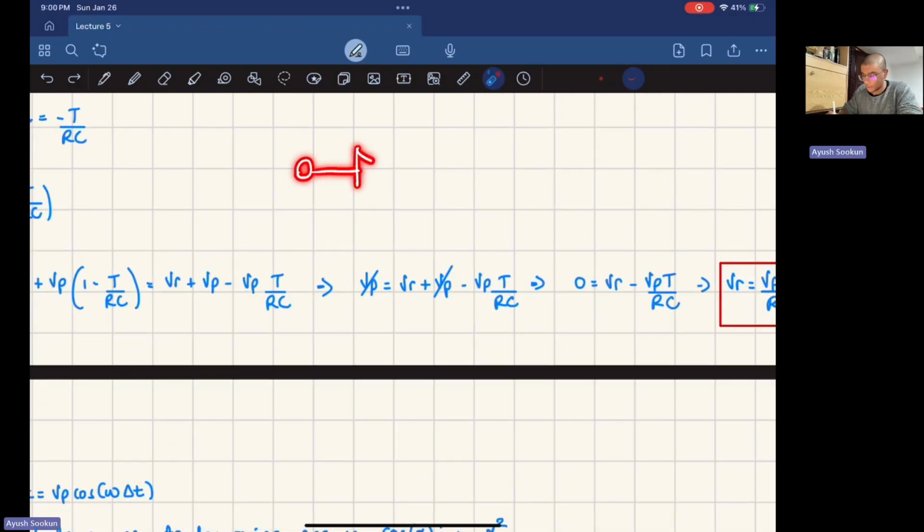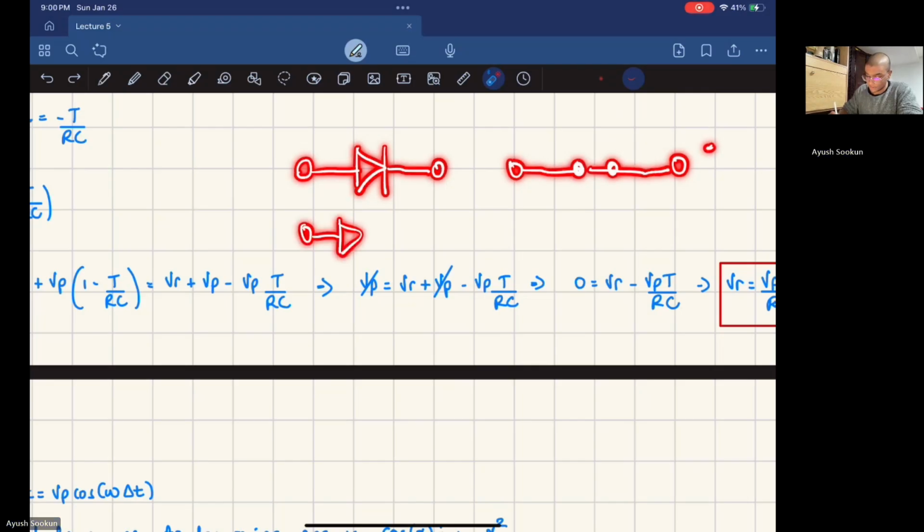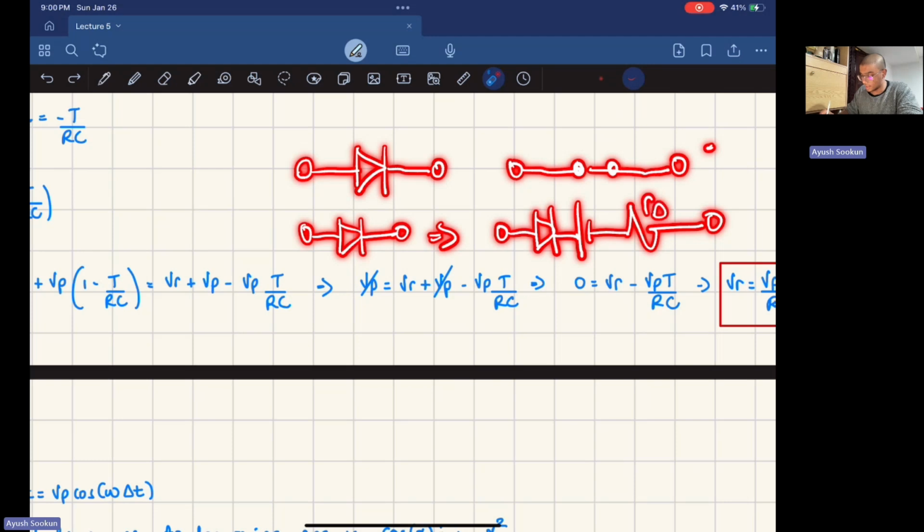So I've got on my screen a diode. This diode, if it's ideal and if it's on, is going to be a short circuit, just like that. However, if this diode is non-ideal, it would be something like this. We have a diode in series with a voltage source VDO and a resistor RD. However, this RD is very, very small, so we can basically assume it to be a short circuit. Okay, that's a classic assumption in this class. You can always do that.